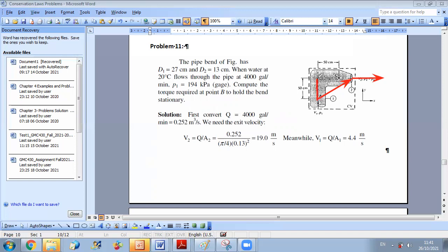Now, if you want to do r vectorial V, it's not wrong. What is your vector r? This is r. You should decompose it into i and j components. Along i, you have this distance. Along j, you have 50. And you will see that when you do the vectorial product, since the velocity vector is along i, this component will cancel out, because i vectorial i will give you 0. So you will just take into consideration the 50 centimeter component.